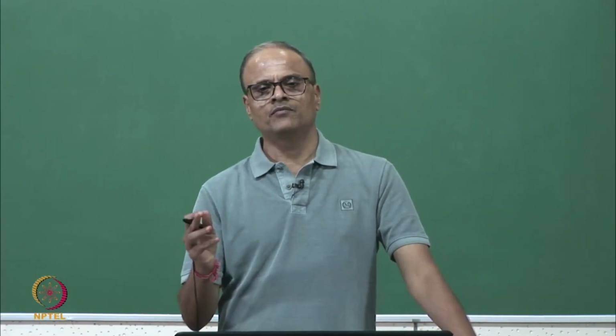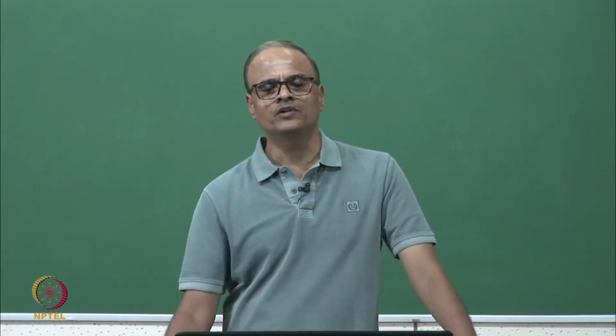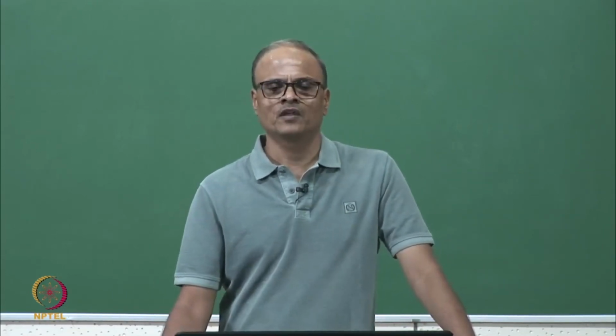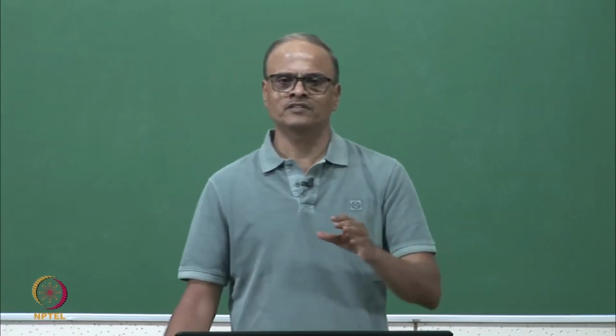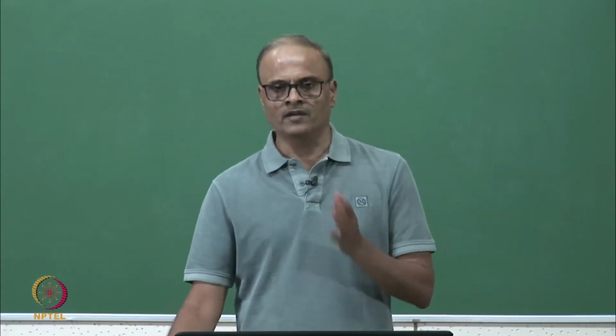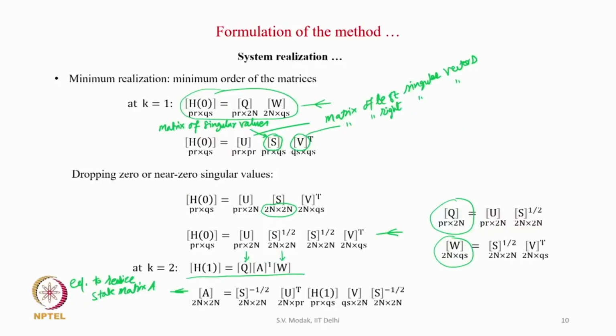Now for the next time instant, we again construct the block-Hankel matrix, and that matrix is designated as H1, which is also used in this equation. In this way we get S, U and V, which are required in this equation, and we also get H1, the block-Hankel matrix. Once that is there, we can compute the state matrix using this expression.